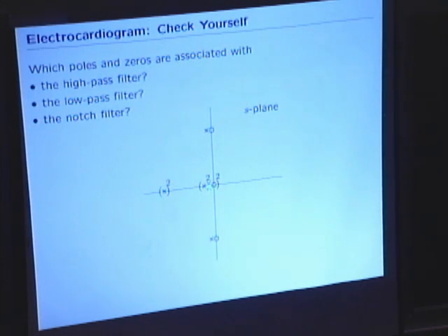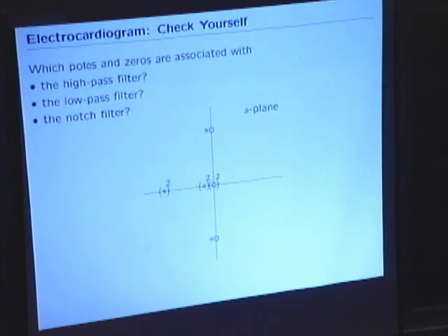then the first thing you have to worry about going left to right on the Bode plot is the zeros doing this, and then these poles flatten out the zeros. So what's this doing? That's the thing that's attenuating the high frequencies, which leaves us with this. What's that? And how do you know it's a notch?